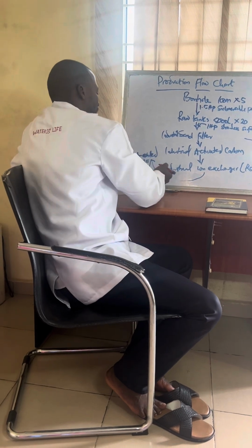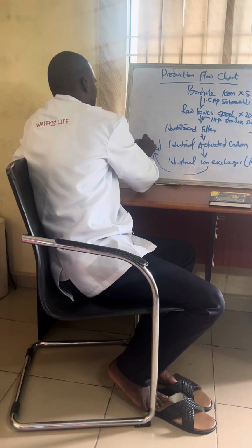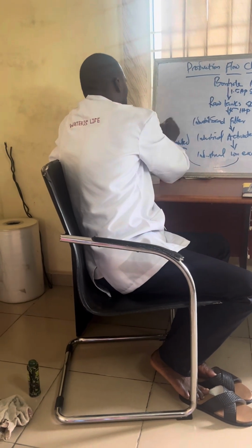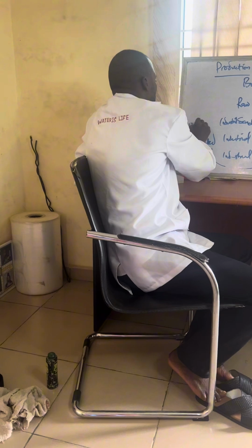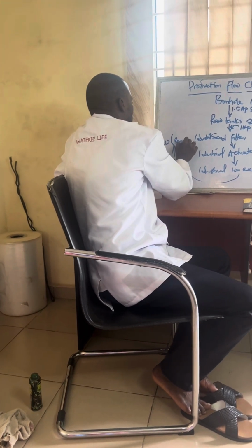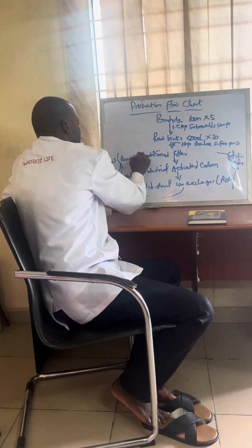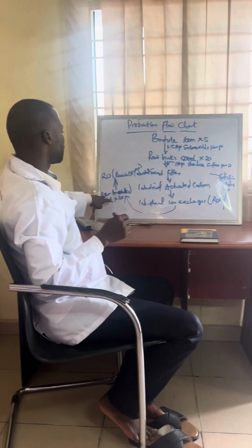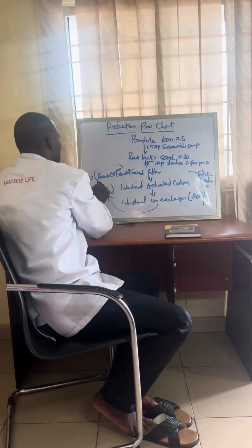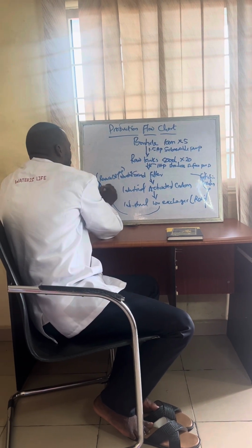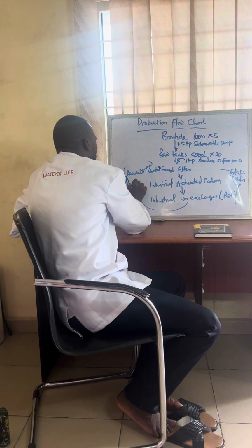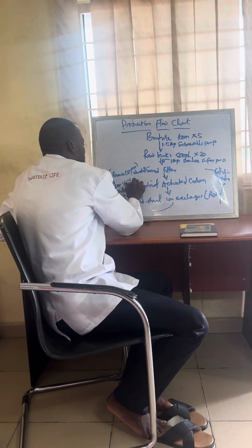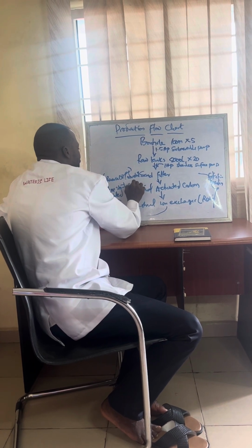Then we now have, it's still moving. It will now pass through your RO, which is your reverse osmosis. Now what takes the water from this pre-treated tank to reverse osmosis? We now have probably a 1 or 2 horsepower pump. Let's say 1 horsepower, still stainless. Remember, in a water factory, use a stainless surface pump.